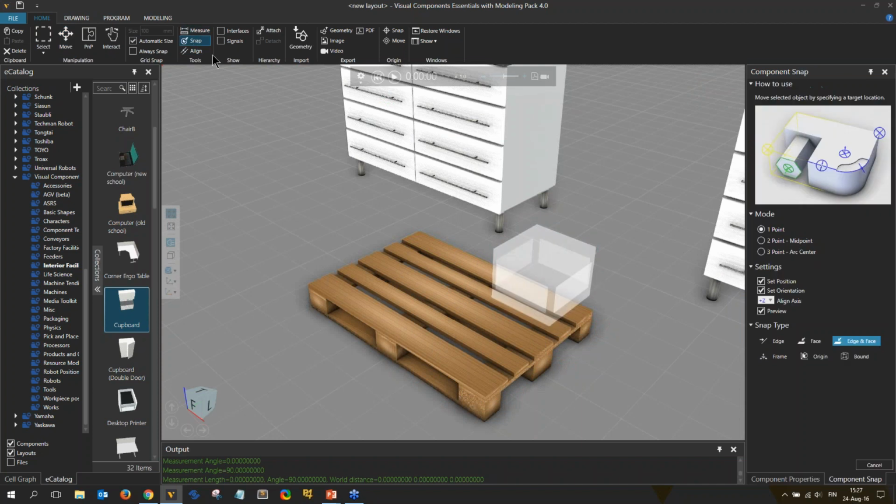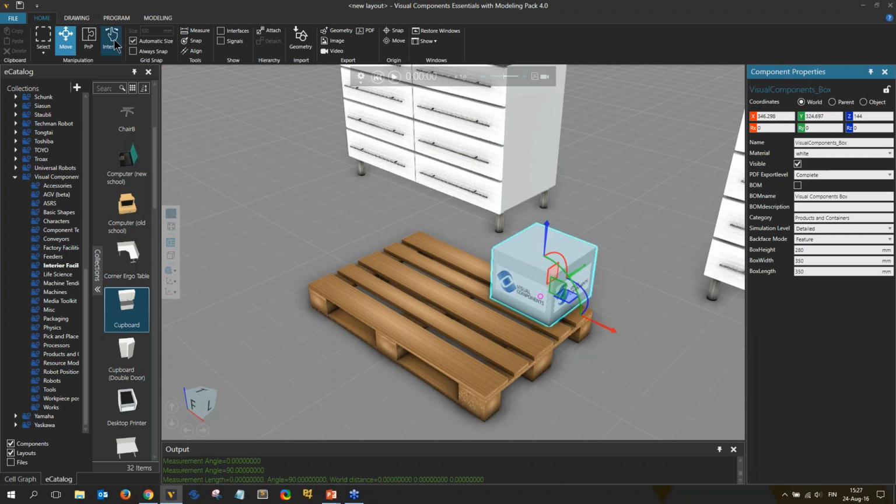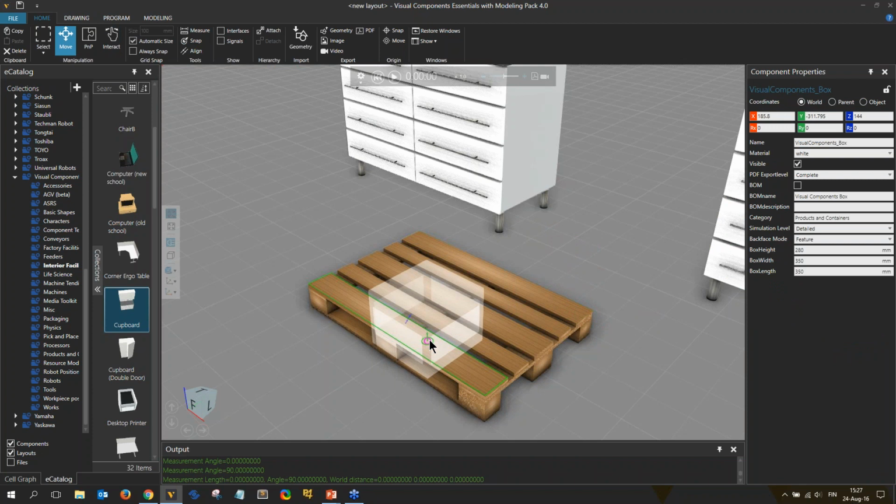And you can also filter out what kind of features you are allowed to snap in 3D. These settings are the same settings that will work for the pink donut. So if you change these settings here, remember that in here you will use the same setting. So if, for example, you disable the orientation snap, it won't do the orientation snap from the pink donut either.